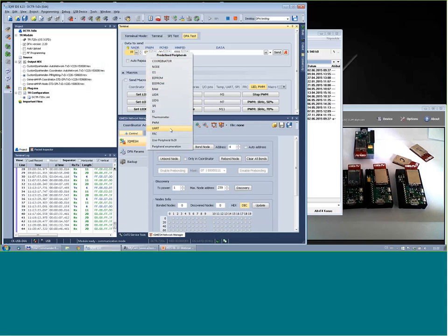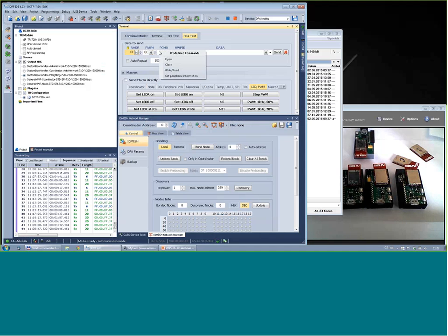So basically, if you have a device that you want to connect to our module with the UART, then you would just use this peripheral. There is a command to open and close the UART, to read and write, and that's it. Then you would bond your nodes, do the discovery, and say, okay, I want to read or write to the UART on module number 5.